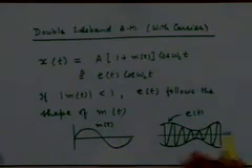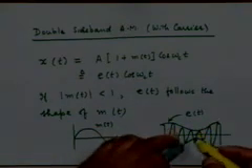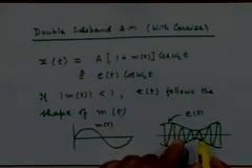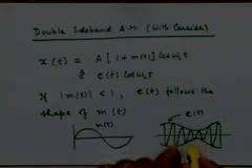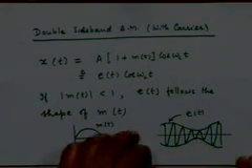The moment it becomes more than 1, the envelope will now become in that region proportional to mod of mt, right, because this portion will go up, this portion will come up. So that's what we don't want. So we define a parameter which is called the modulation index or depth of modulation.